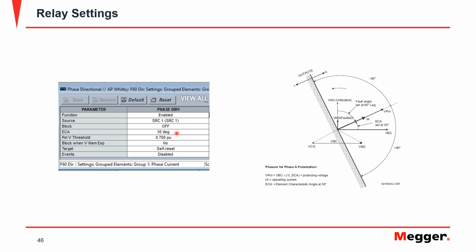Of course, once you've done this a few times, you know to go to the user manual and look, because you cannot assume that this means what you think it means. Some would think that this is the MTA, because this is how most of these relays you are used to configuring.